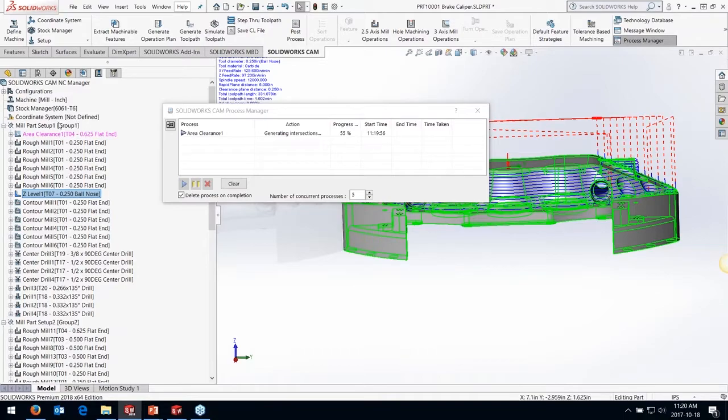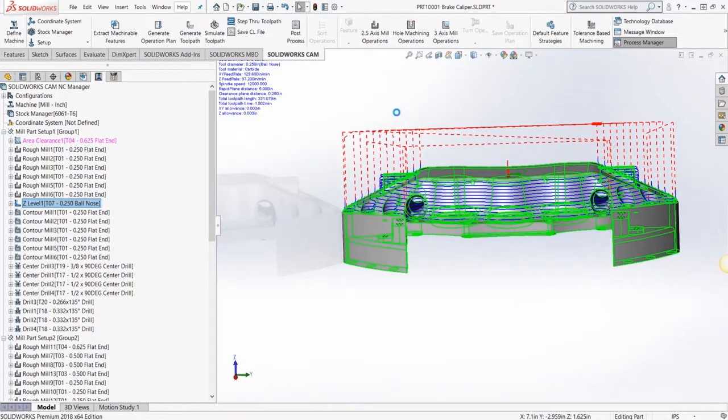And it's going a little deep for my tooling right now, so I can always go in and modify anything. We've got full control over it. It's a full CAM package. It's not restricted anyway. If you've been using CAMWorks for many years, like I say, started in '97, essentially you've got the same controls as CAMWorks. You've got all the ability in here to go through and limit the depth of cuts, change the step downs and everything else in here.